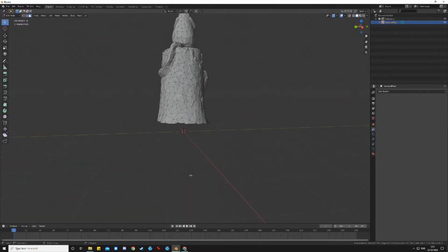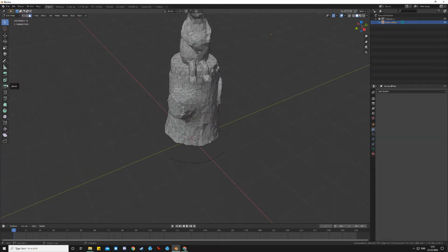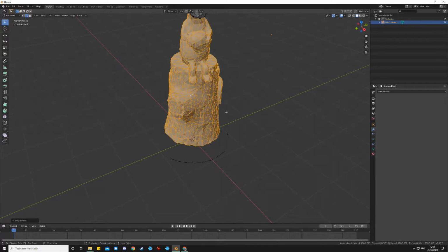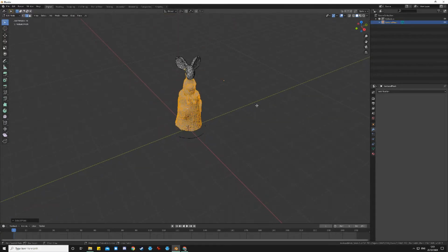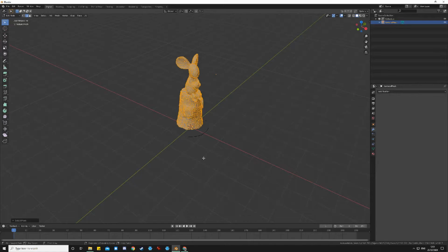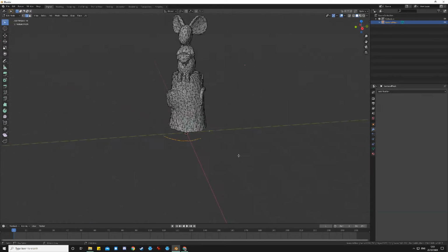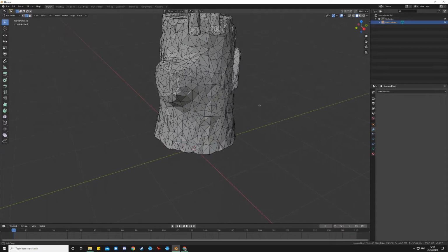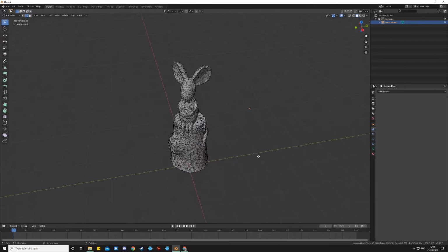Great. Oh, that's interesting there that there's some edge left. This can often be the case. Sometimes I do this trick where I actually select just the main object, and I press Control and plus, and this is what we call incremental selection. So it will keep selecting everything. I keep pressing plus until it selects everything that is all connected to one mesh, and that means I've just got this selected, and then I do a Control I to invert select, so I've got those extra bits there, and then I can say delete, and they are edges, so I'm going to say delete edges. I usually do that a couple of times throughout the process just to make sure that I'm just working with this object.